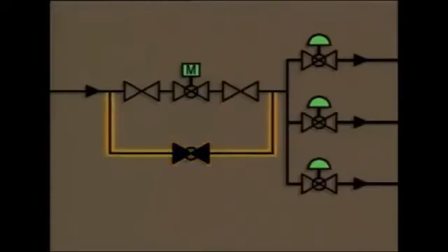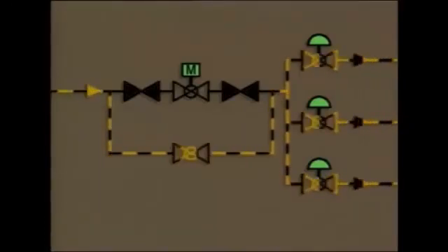The line it's in is a bypass line, and the valve functions as a bypass valve. We've indicated that the bypass valve is closed by filling in the symbol. This is a common way to indicate that a valve is normally closed while the system is operating. The bypass valve can be used to control flow manually if the automatic control valve malfunctions. If that happens, the isolation valves can be closed and flow through the supply line can be adjusted manually using the bypass valve.